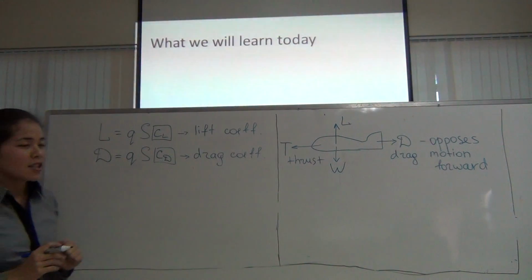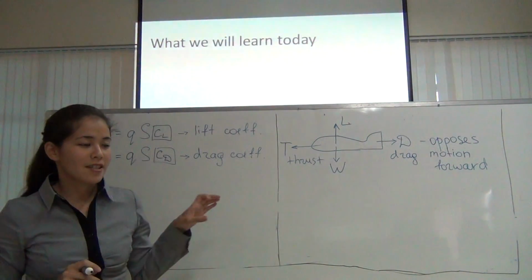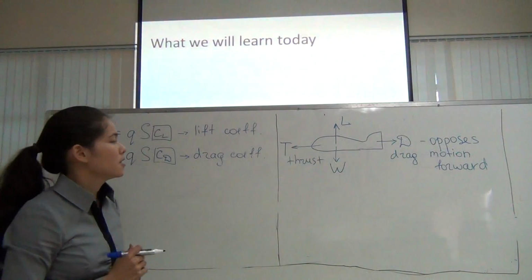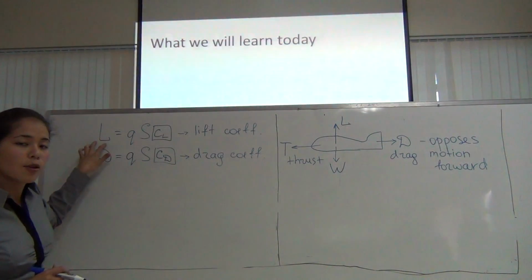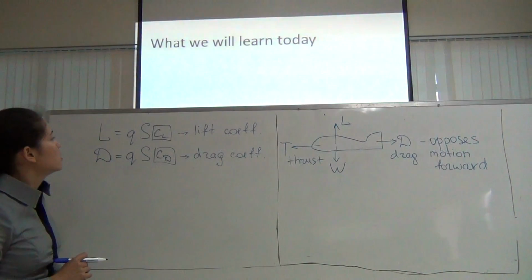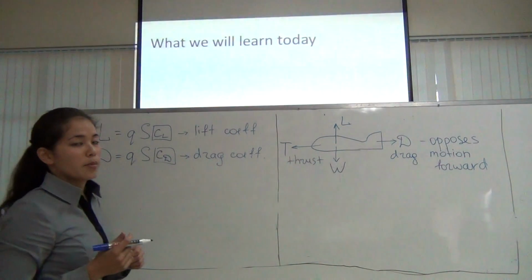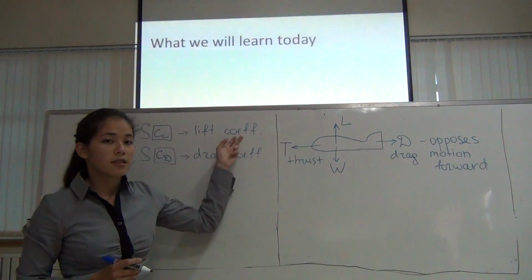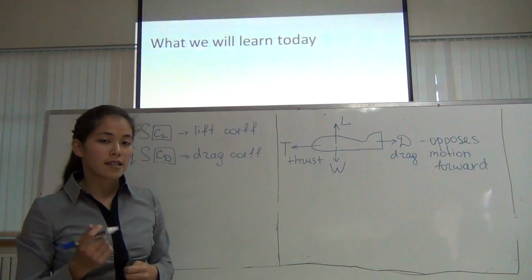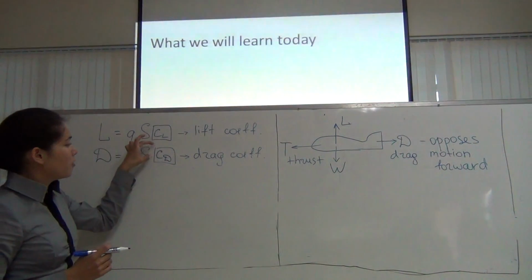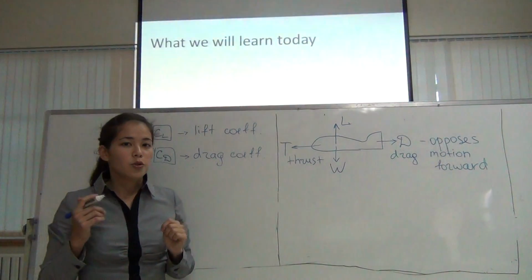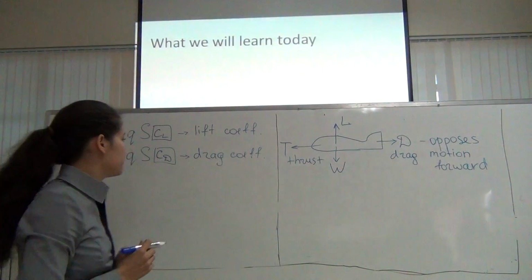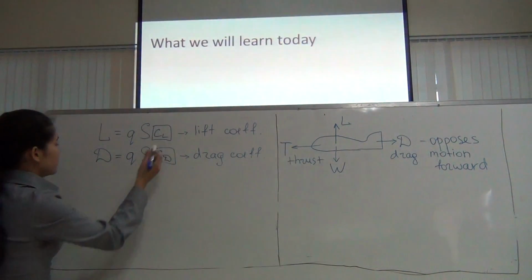Now, imagine if we had two airplanes, one very small that fits into a wind tunnel, and the other one is Airbus A380. If we calculate lift, they will be drastically different from each other. So we cannot make any conclusions by just looking at the value of lift. But CL is a coefficient, so that means it is dimensionless. And these two coefficients enable us to understand how good the airfoil performs. So these are called performance parameters.